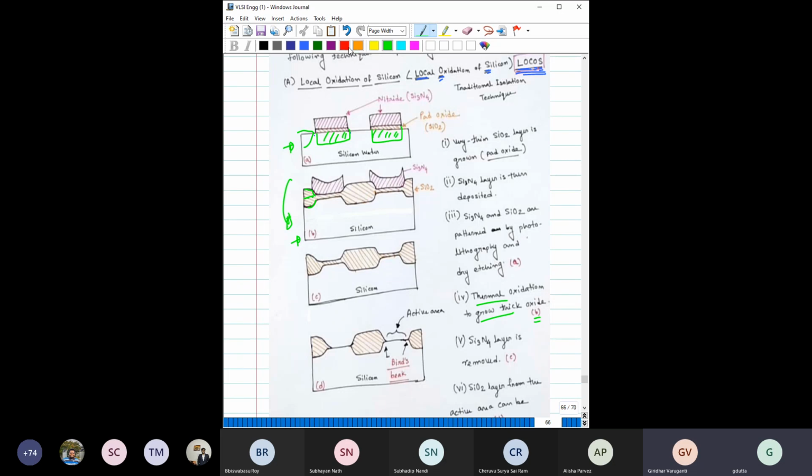Maybe on top of this oxide you can take one of the contact lines, because you have to route the contact line on the wafer surface. If you route it over a thin oxide, then easily a channel can be produced below it, because you have some potential on this line, and that may create some issue. But as the oxide is thicker, its threshold voltage is very high, so probably at this voltage no channel will be created. So that is one advantage of using this thicker oxide.